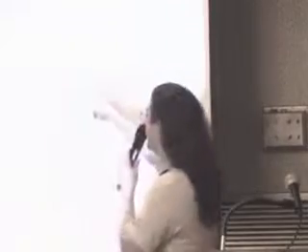Another method, which is starting to come into common use, uses a method just like these projectors here. You shine a light through an LCD or digital light processor, those little micromirror things, to project an image onto the paper. The problem is, if you look closely at these things, you see a little screen door effect, because there's a little gap between the pixels.